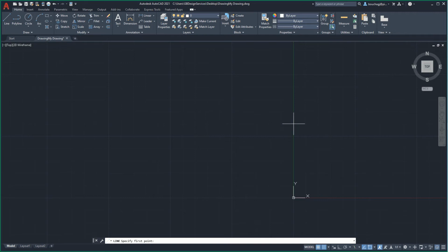If this is advantageous to your drawing task, then activate this tool. Otherwise, this tool is best left inactive. Simply left-click on the Snap Mode icon to disable the tool. Pressing the F9 key will also toggle this tool on and off.